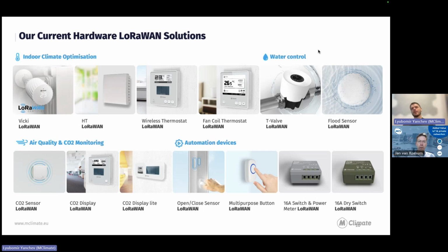So the fan coil unit is kind of the most basic heat exchanger. There's a coil, and then there is a fan behind it. Through the coil, hot or cold water is pumped, and then the fan just blows into the air, into the room. But the fan coil thermostat features a large e-ink display again, and it's compatible with 2-pipe or 4-pipe heating systems. I call it a hotel thermostat because it's compatible with most of the existing hotel thermostats.